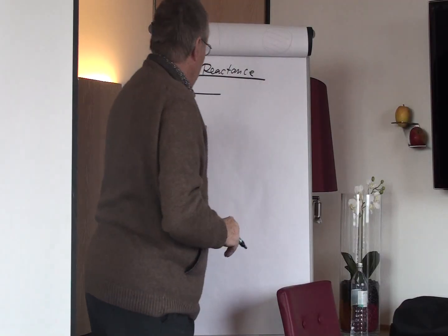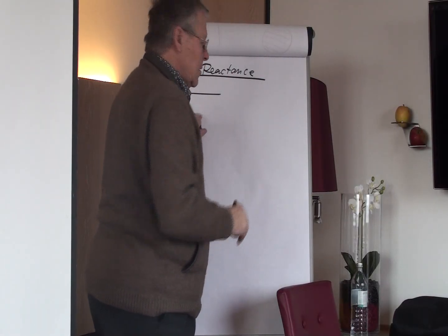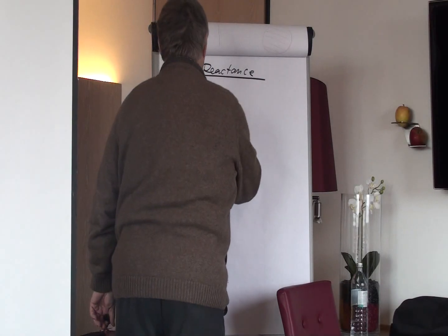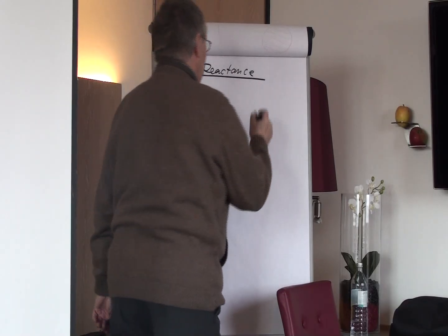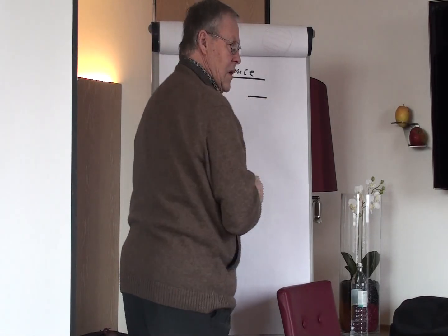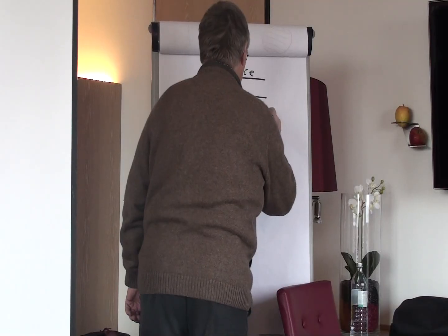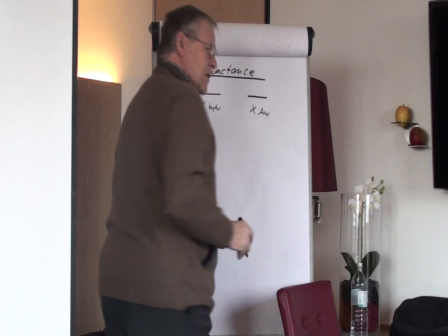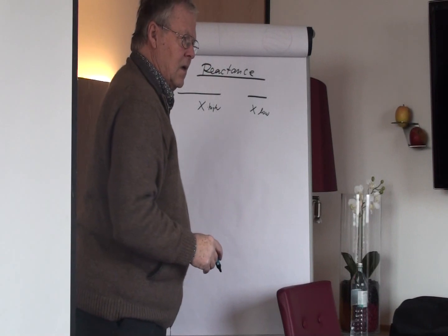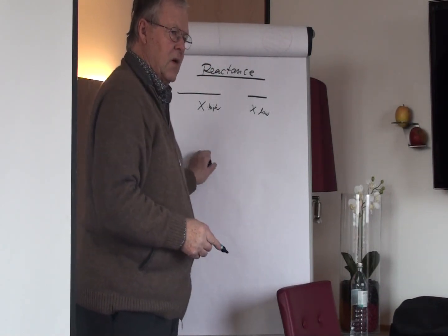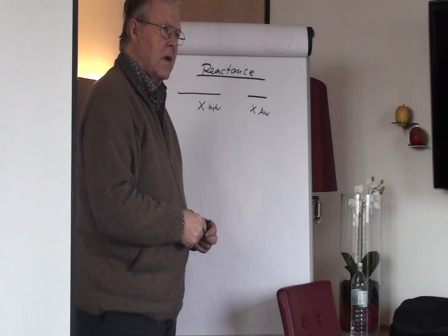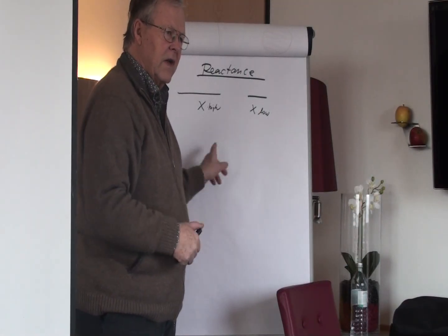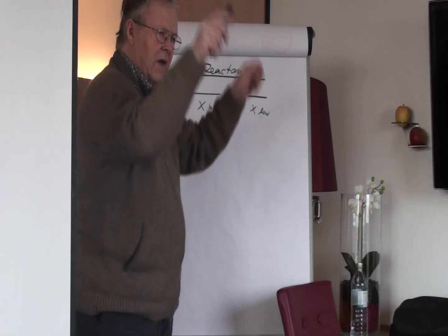If you have a long electrical cable, the reactance may be high. If you have a short one, the reactance may be low. So this is clear, okay? Length is the most important factor. And most of the reactance is sitting in the flexible cables, if they are 10 meters long.